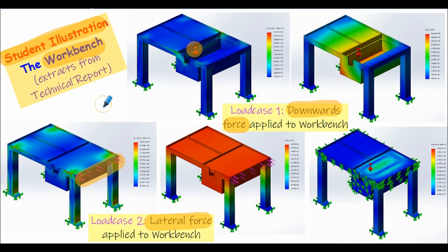Why are there no compressive stresses in this model? That was something the student needed to investigate and effectively try and verify the model. I'm not criticising the student here because he didn't actually have to undertake this exercise. He did this of his own volition, a highly motivated student, and obviously very proficient using his CAD package. But then on using the inbuilt finite element software, he really needed to verify his output to ensure his results were as expected and so were valid.